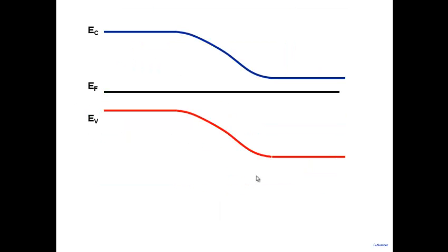All right, one of the things that we see in the energy band diagram is that there is a barrier here. Why do I call it a barrier? Well, this is n-type. I have a lot of electrons here. For these electrons to go over to the p side, they have to cross this particular barrier. They have to go up in energy, and going up in energy means encountering a barrier for electrons.